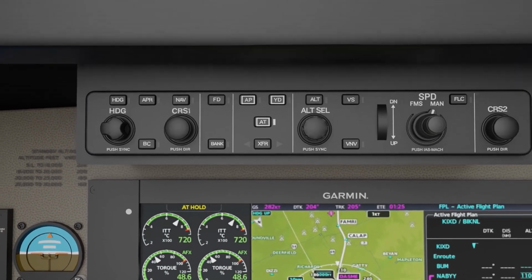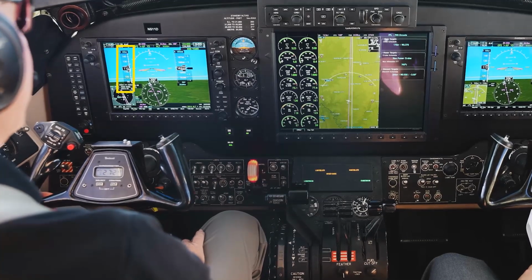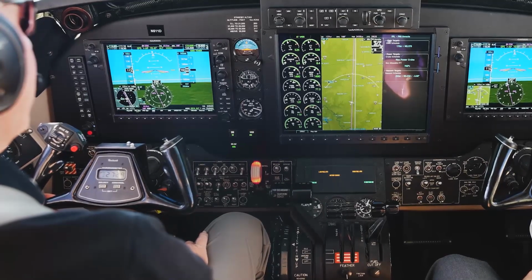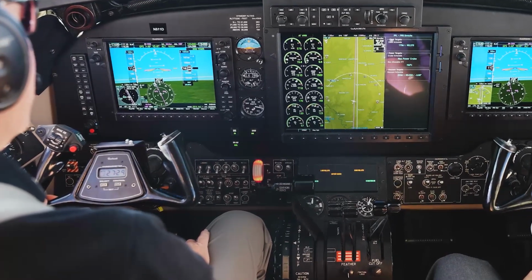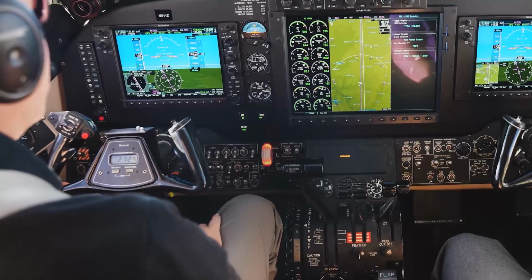To engage the autothrottle, press the AT key on the mode controller. This will arm the autothrottle on the ground or engage it if airborne. Pressing the AT key in air will engage the autothrottle in a mode that corresponds with the current vertical flight director mode. In addition, the autothrottle is continuously monitoring system status and will automatically engage if it detects a torque or ITT exceedance, an underspeed or overspeed condition, or an activation of emergency descent mode.